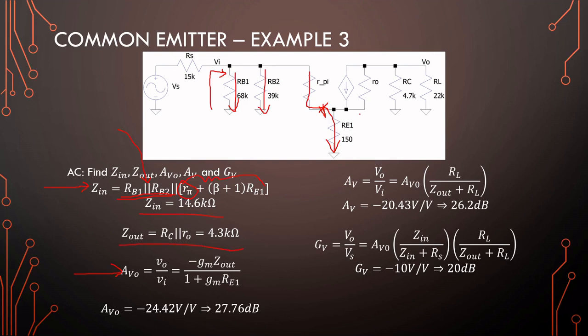The output impedance we do not see in this direction, right? So right here is kind of a virtual ground for our source. So our current source is driving everything on this side. The other way to look at it is this resistance is so small compared to R out that we don't even bother with it. Okay, so your output impedance will mainly be RC with R out going towards infinite in any case. Okay, so RC parallel to R out remains our output impedance.